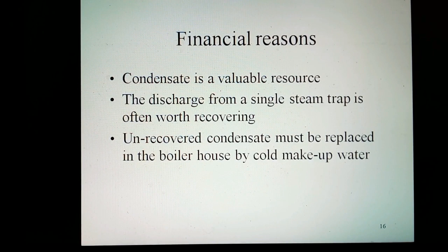Condensate is a valuable resource, and even the recovery of small quantities is often economically justifiable. The discharge from a single steam trap is often worth recovering. Unrecovered condensate must be replaced in the boiler house by cold make-up water, with additional costs of water treatment and fuel to heat the water from a lower temperature.